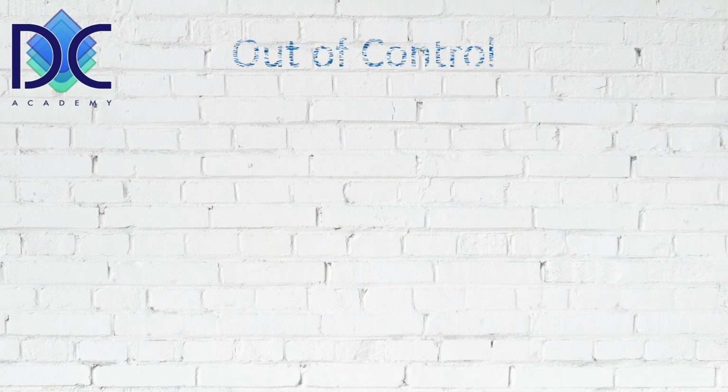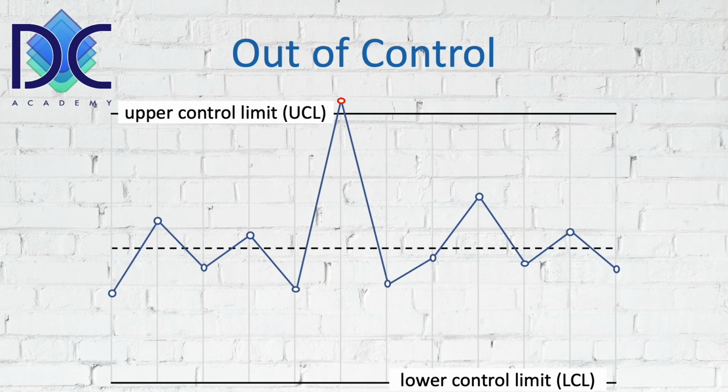The last element that we can have is that the process is out of control. This relates to the fact that the sample average that we are evaluating, or that we found at that moment, is outside of the control limits. In this case, it's above the upper control limit, but it could also be below the lower control limit. Those are two elements that we have to avoid, and we have to be very careful with those. So basically, when we see the out of control warning here, we have to stop the process and find out what is wrong.